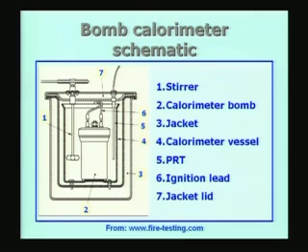In the subsequent experiment, I am going to use whatever fuel I want to get the heating value of the fuel. I can use that fuel in the form of a pellet and repeat the experiment, and whatever C value I have determined in the first experiment, I am going to use as the C value for the second experiment, and therefore I will obtain the unknown heating value in the second experiment. This is the basic idea.